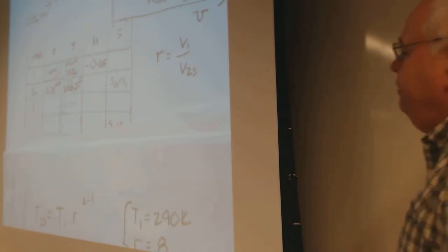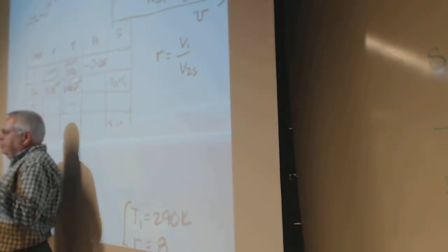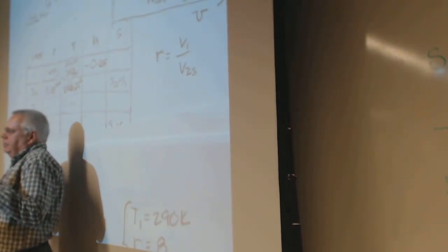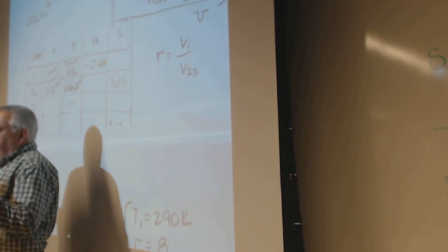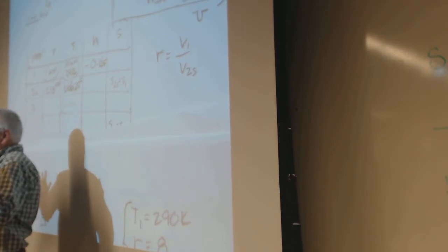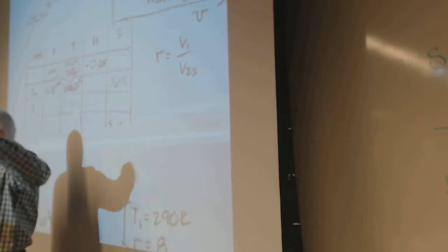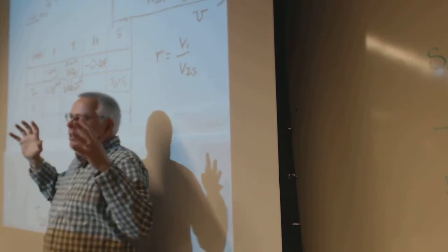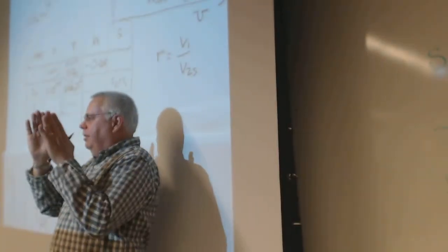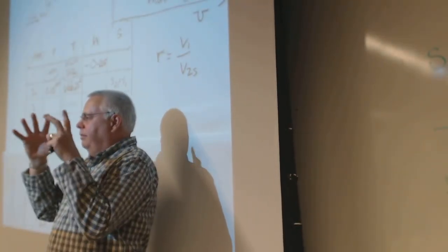But the pressure and the temperature both went up, and it didn't go up by a factor of 8. This went up by a factor of 18. That's the thing about when you compress gas, it heats up, and because it heats up, the pressure rises. It's not like water. The whole thing with air, with the ideal gas law, is give it 1/8 the volume and the pressure goes up more than that if you contain the heat.